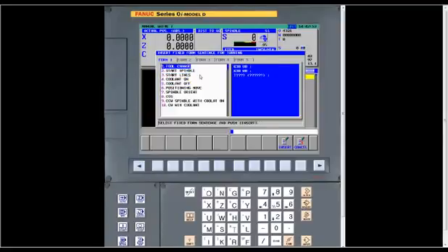As I said, Form 1, these are start of the program type commands. And what I do in Form 2, usually I set up cut speeds for different types of material. As you can see, I've got mild steel, I've got stainless steel, aluminum, cast iron, preheat treated, brass roughing, and then finished feed rates and cut speeds for that also. And number 3, I've got drill cycles, tapping cycles, turning cycles, threading cycles, where if I don't want to use the cycles within Manual Guide I, I can just go use these, just paste them in.